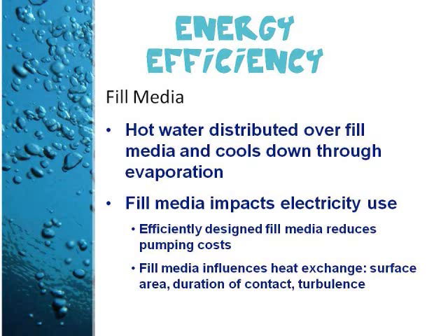An efficiently designed fill media with appropriate water distribution, drift eliminator, fan, gearbox, and motor would therefore lead to lower electricity consumption. Heat exchange between air and water is influenced by surface area of heat exchange, duration of heat exchange, and turbulence in water, affecting thoroughness of intermixing. The fill media determines all of this and therefore influences the heat exchange. The greater the heat exchange, the more effective the cooling tower becomes.